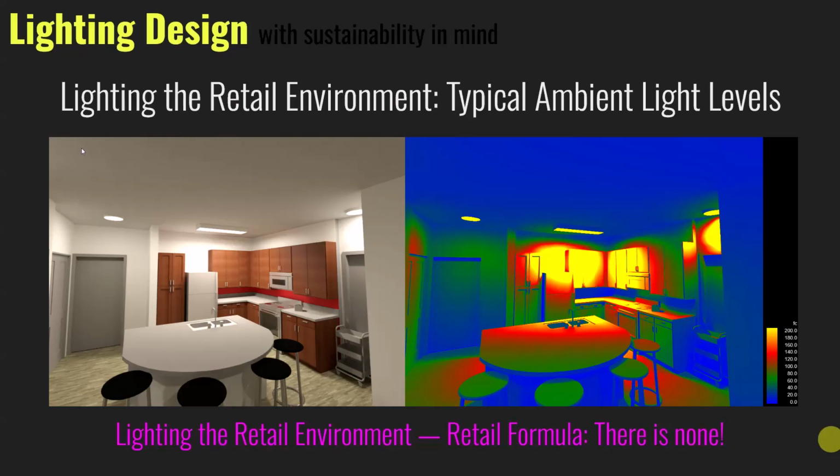The darker the color, the more the foot candles are not going to bounce off the wall to give more luminance. So the darker your color scheme, for instance, the less foot candles are actually going to be produced or bounced onto the things that you want to do. So if you have a really dark, moody space, you're going to have to bump up those foot candles more. Whereas if everything's light, then it's going to be pretty easy and more predictable what the foot candle performance will be in the actual space.